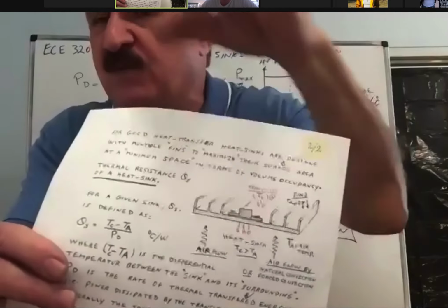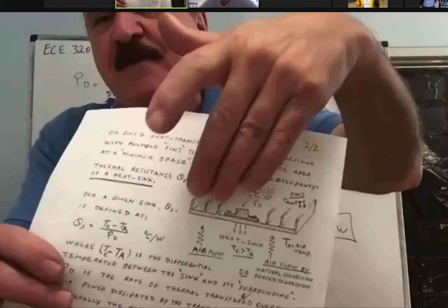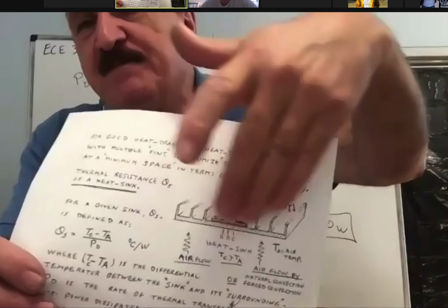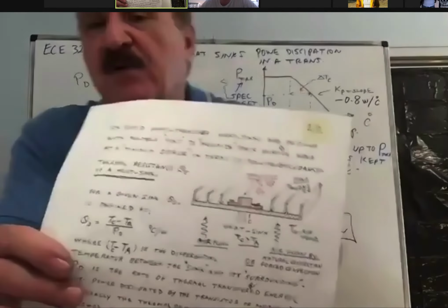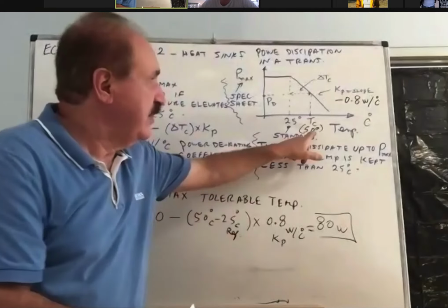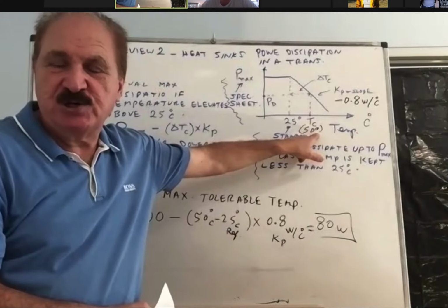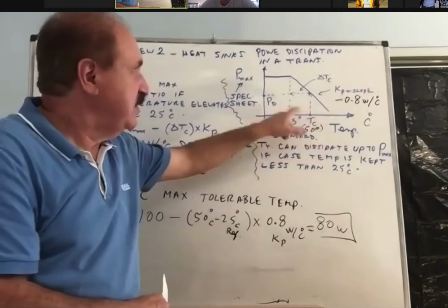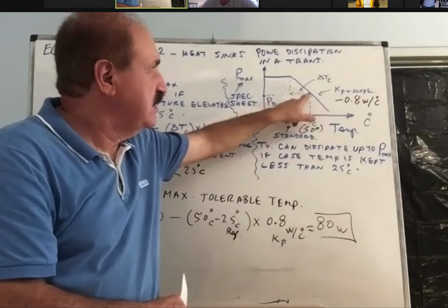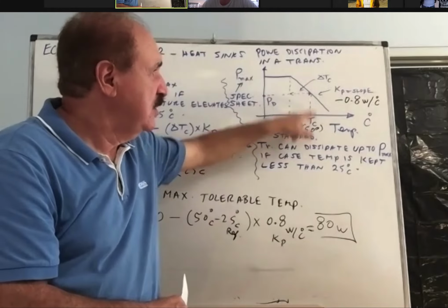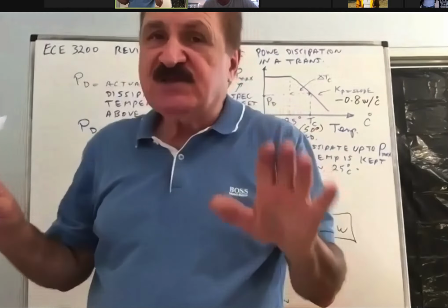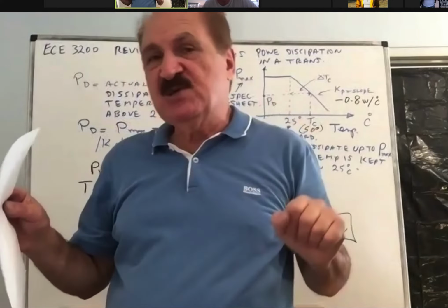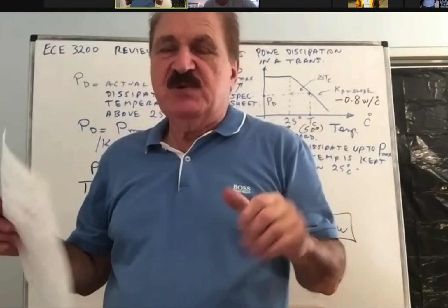We have to design so that the equilibrium temperature will be our computed operating case temperature under the load. So if it is dissipating 50 watts in this example for the transistor, the sink temperature is planned not to exceed 50 degrees Celsius.